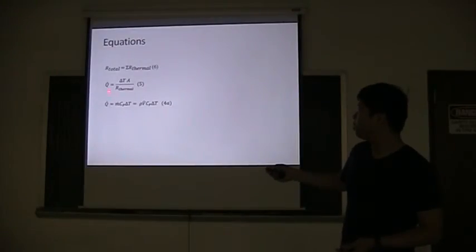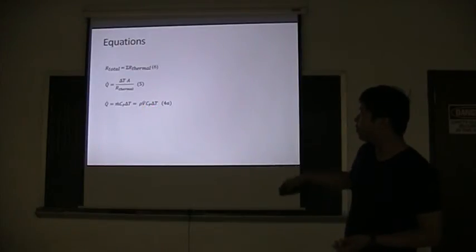And then once I solved for Q, I used this equation. It was assumed in our manual that they simplified this to 1.08 times the difference in temperature and volume flow rate. I don't have that up there, but it's in the manual. And then we just solve for the volume flow rate.